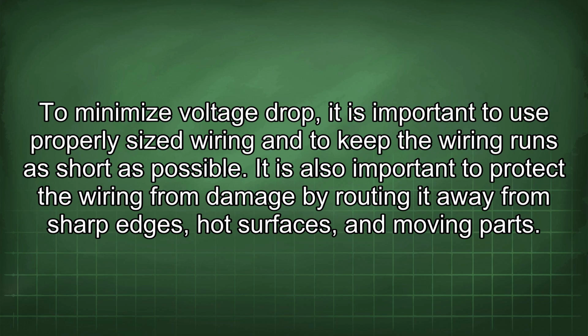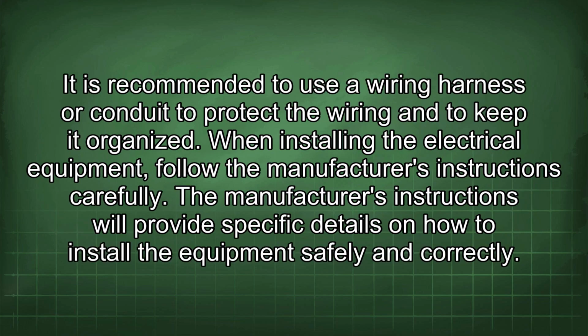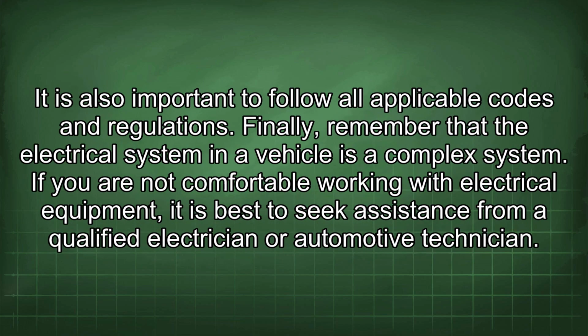It is also important to protect the wiring from damage by routing it away from sharp edges, hot surfaces, and moving parts. It is recommended to use a wiring harness or conduit to protect the wiring and to keep it organized. When installing the electrical equipment, follow the manufacturer's instructions carefully. The manufacturer's instructions will provide specific details on how to install the equipment safely and correctly. It is also important to follow all applicable codes and regulations.